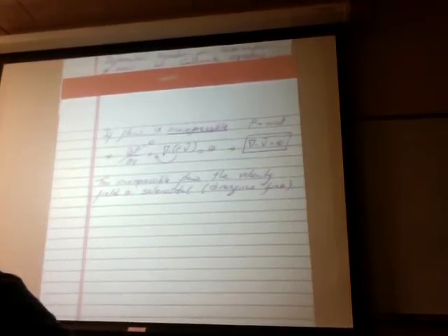If I tell you that in incompressible fluid flows the divergence of the velocity is equal to 0, that doesn't make any physical sense. Okay, why is the divergence of the velocity equal to 0? Well, it's all a consequence of everything that we did here. The velocity field has to be divergence free. That means that the derivatives of the velocity in every direction of the vector field all have to cancel out in order for there not to be accumulation, for the flow field to be incompressible.